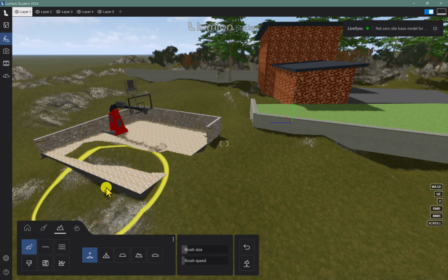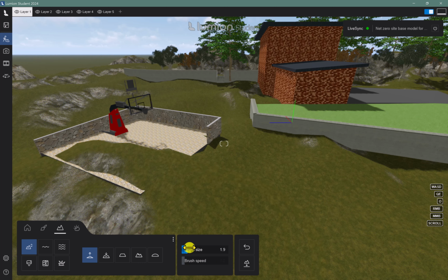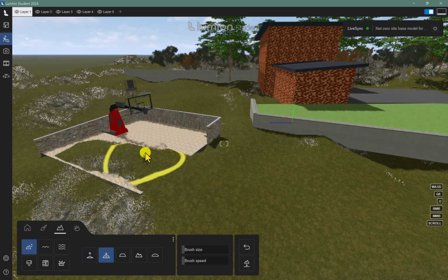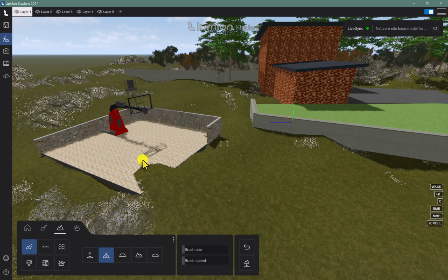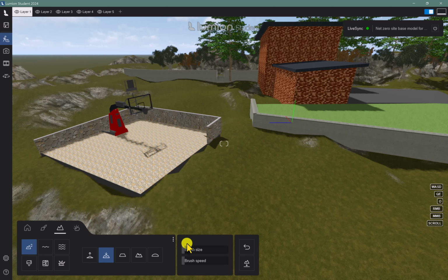And one thing that you can do is back in Revit, you can control the height of things like the patio area so that it is above the adjacent landscape. You can even just add a little bit of thickness onto it. And it does take a lot of patience to get it to be exactly right.